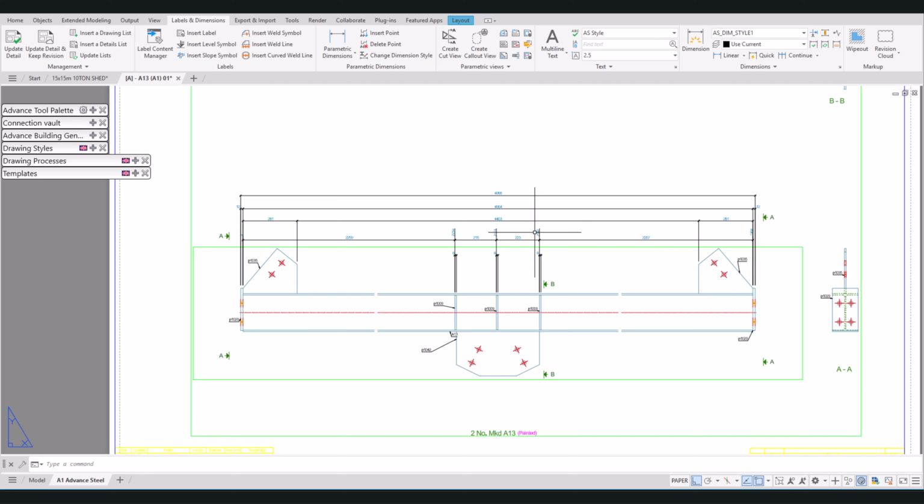So I was taught how to do my dimensioning through the yellow book. That's the South African standard. I think it should be the Steel Detailer's Manual. It's a yellow book. So they said you dimension going outwards. So you start with the line with most dimensions, you go to the line with less dimensions.